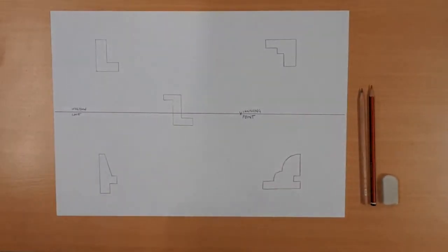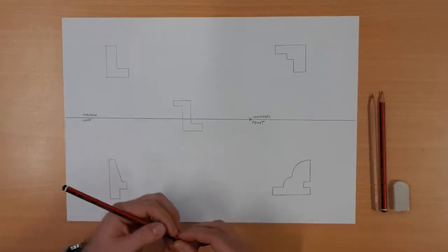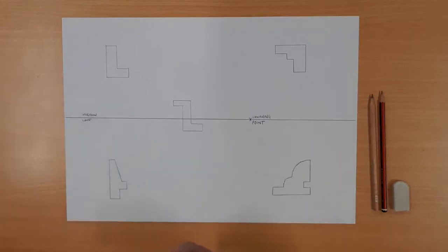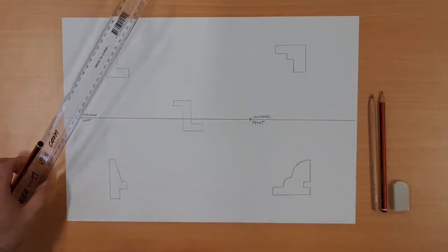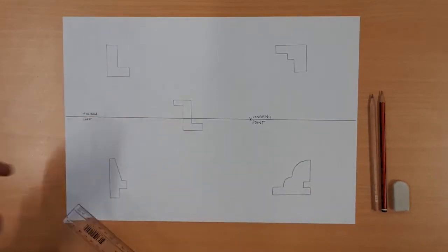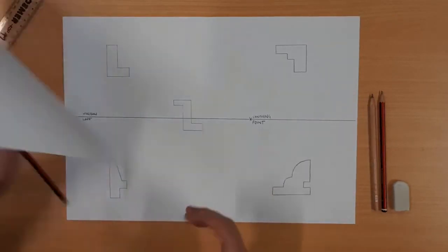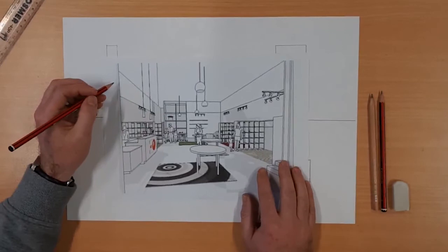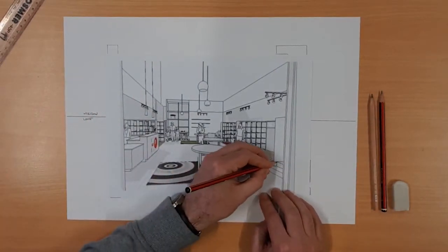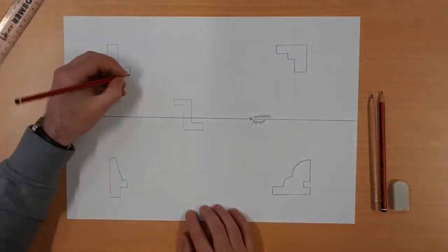So let's begin. Once again, I'd be using your 2H pencil, especially at this step. Keep them really super light, really sharp pencil, because you're going to be erasing a lot of construction lines or guidelines. I'm going to begin with this shape that I started before, and with our image, you're only going to be projecting back or receding lines back wherever there is going to be an edge. So I first of all identify where all the edges are.